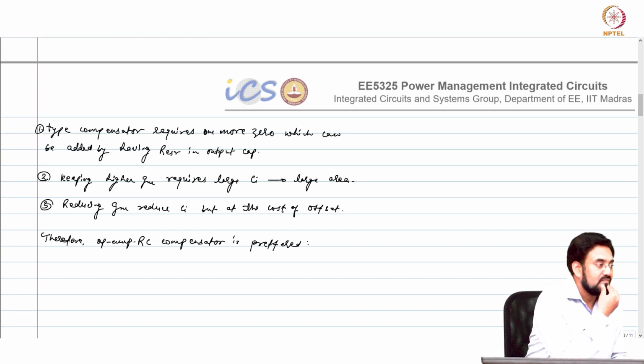Okay, but that doesn't mean we don't use GM. You can use GM still. Let's say with 100 micro ampere per volt you can achieve the offset you are getting, it's within your spec, then you can go for it, that's not a problem. Okay.